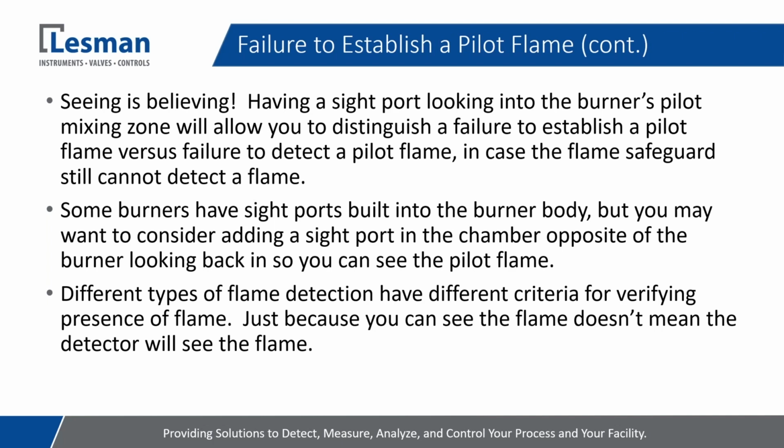So this is more of a failure of detecting it, but it emphasizes the importance of having some kind of a visual element to the pilot flame. Not every single burner has a sight window looking back in. So if that burner's not designed for it, we would certainly recommend that there's some other port installed looking back into the flame.